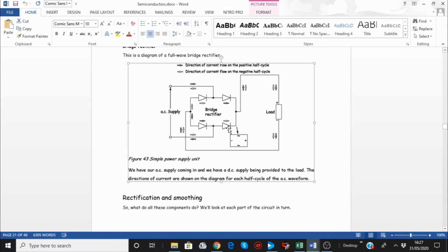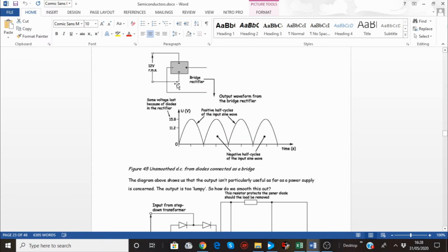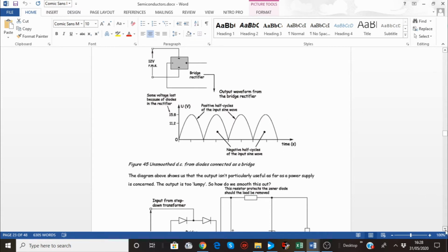So there's always going to be 2 off, 2 on, which is good also for cooling down the diodes. So the current comes through the load the same direction and goes back to the source through this other diode back to the source. So that's how it works. The same with the bridge diode. You get positive bumps, varying DC voltage on the output.